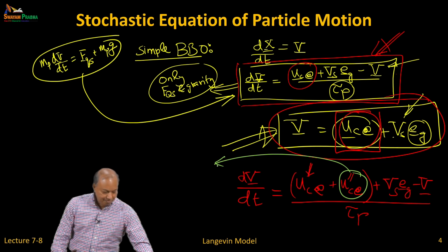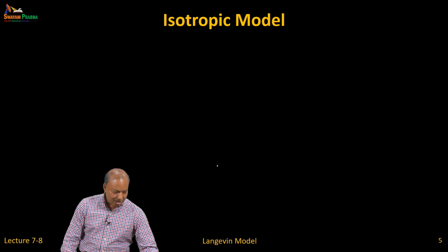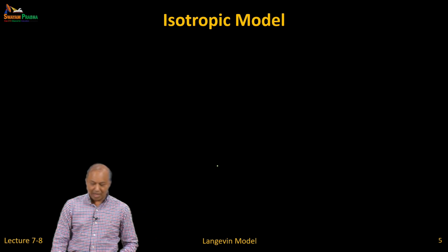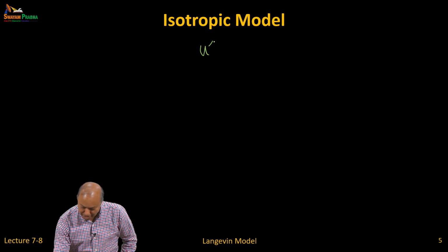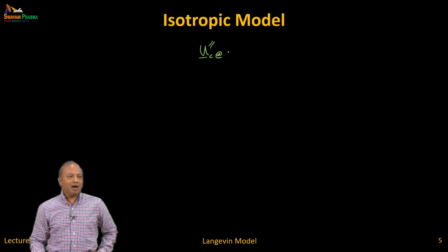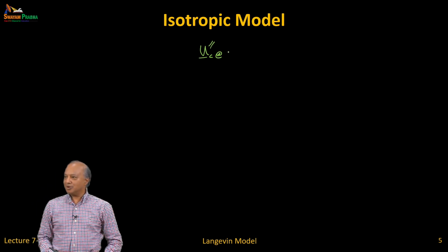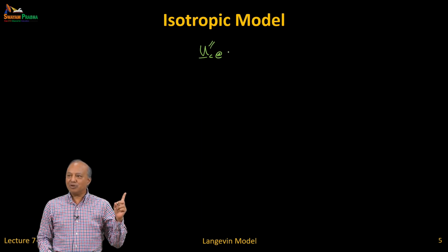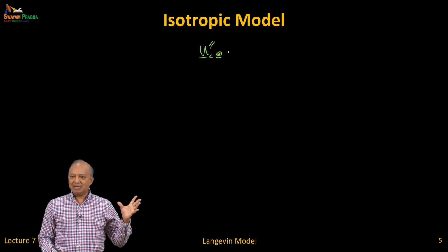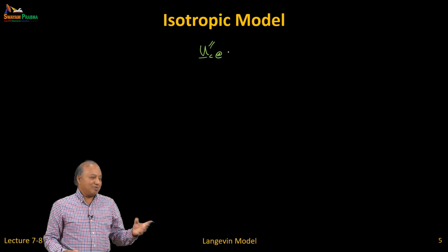The other thing is this model comes from Pope's original idea. So what do we need if the turbulence is isotropic? The question is, what should we desire from this quantity? So I reduced the problem to saying that we need some random numbers to be introduced. What kind of random numbers? Previously you remember its mean value was 0, and the variance should be equal to delta t. Similarly, there must be some restrictions on this.